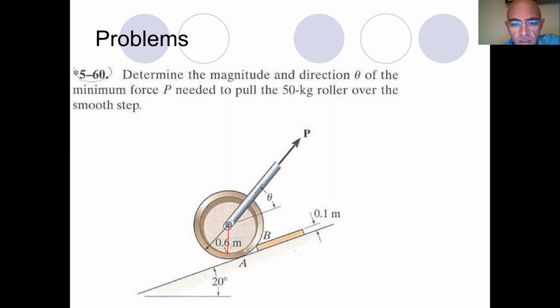First of all, we have the weight, and there exists a force coming from the step. Now, there is a critical point. Of course, there is another reaction force at A, but the thing is this. Remember that these are contact forces. So the forces at A and B are contact forces. Therefore, they are perpendicular to the tangent of the surface.